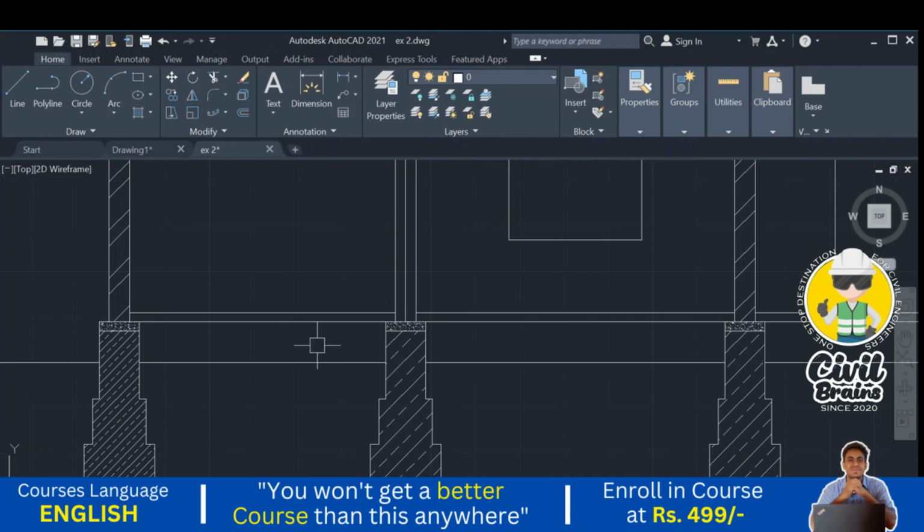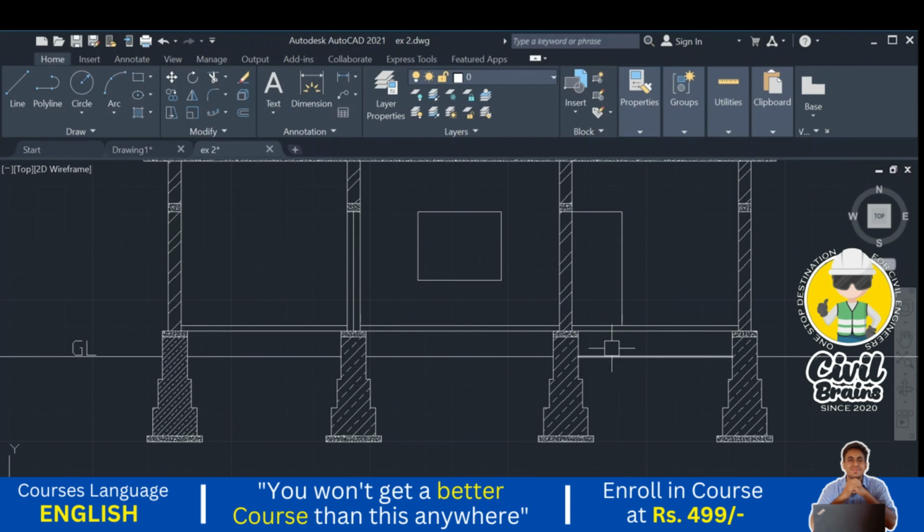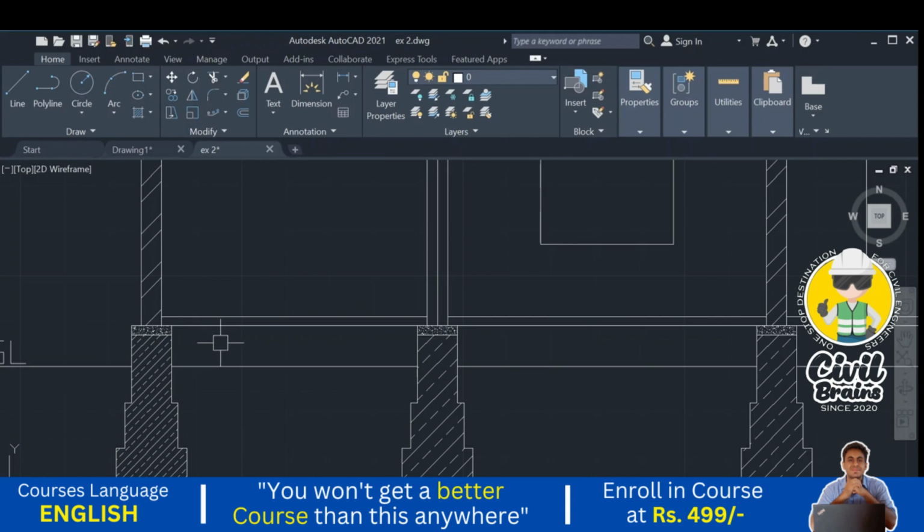Here we need to fill the sand or we need to fill the soil. Okay, we need to fill the soil and we need to compact that one. Once we fill the soil, we'll just compact. After the compaction, we need to put the DPC over this.